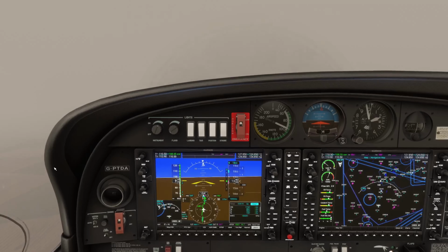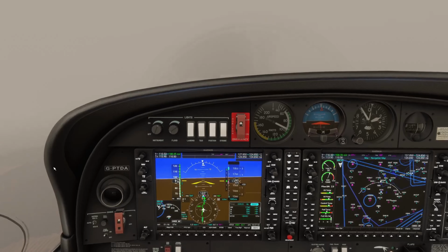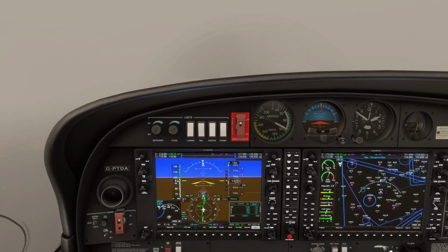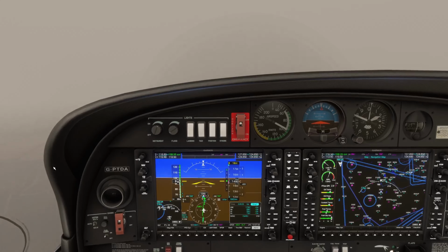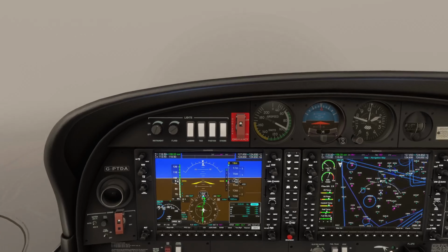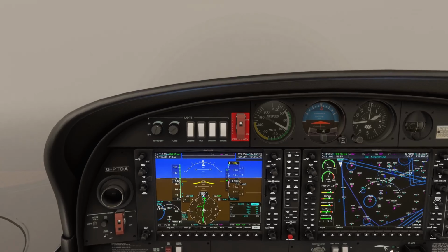So we're also going to do a quick check of the chart. So 5 miles, we should have been at 1800 feet, which we were. And we're simply just monitoring this down the approach now. So I'm going speed, glide slope, localiser. Speed, glide slope, rate of descent, localiser. And we're simply maintaining that all the way down the approach path.